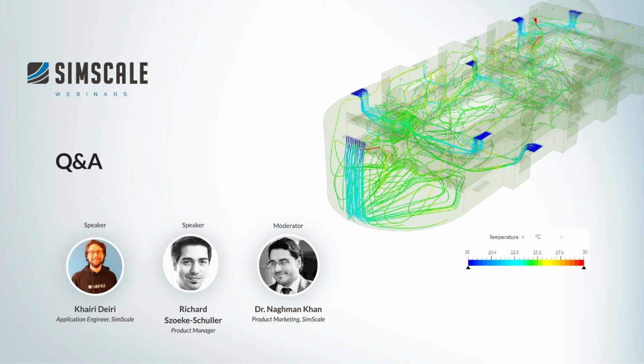For example, if you have a wall, it automatically defines boundary layers on that wall. If there's an inlet, we do a refinement of the cells towards the inlet domain, from the outside. So we have a refinement there where we expect the flow to come into the domain. There's a bunch of different automations we have in the background that make sure that the default mesh you get from SimScale without much user interaction is already a pretty good mesh to start with and will be sufficient for most of the cases. And you can just decide if you want to start very coarse or already go with a fine mesh.